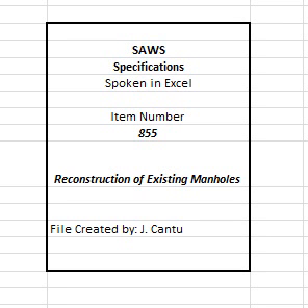855.6 Testing. The contractor shall notify inspector and engineer 48 hours prior to beginning of manhole testing. 1. The contractor shall perform the testing for all sanitary sewer manholes in accordance with the following. 2. All manholes must pass a leakage test. 3. The contractor shall test each manhole, after assembly and backfilling, for leakage, separate and independent of all other sanitary sewer piping, by means of either a hydrostatic test, vacuum test, or other methods approved by the engineer.